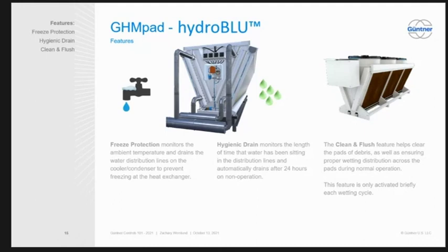So there's no point in using water. But on dry days, it's very effective. So we take all those things into consideration, and we put water across the pads to make them as efficient as possible. Another thing is, we do record internally how much water is being used in this unit. So if we ever come across a problem where this unit's dumping a ton of water, let's go in there and find out exactly how much water it's used. We can do the calculations and figure that out.